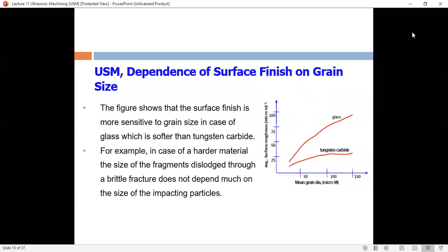So, will the slurry be recycled back to the machine or disposed after use? Basically, the slurry will be recycled, but there is preventive maintenance. Based on historical analysis and so on, the operator should know how long you can use and recycle the slurry.